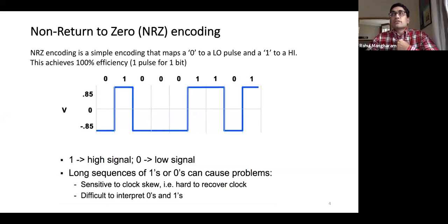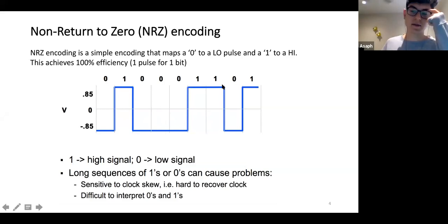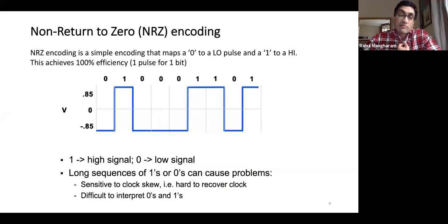Yeah, so the reason why you have that, in this slide, the problem is that we do not know the bit boundaries over here explicitly because we have no change in the signal here and we have no change in the signal here. So we need to have enough changes in the signal because we are trying to communicate both the data and the timing, right?